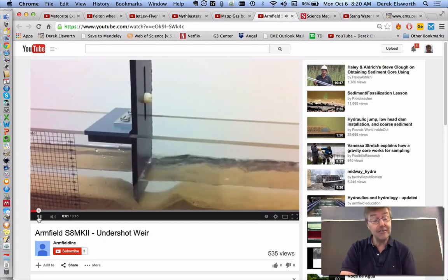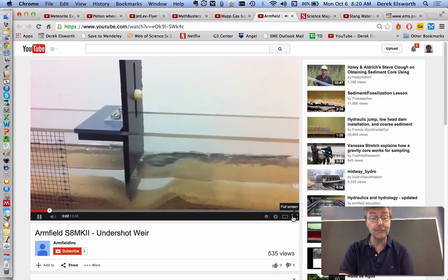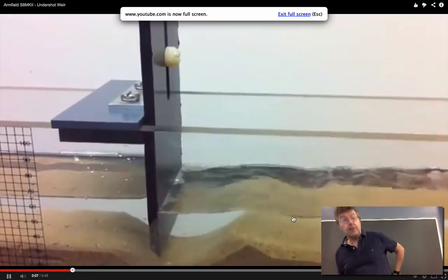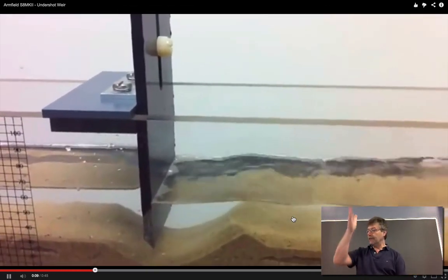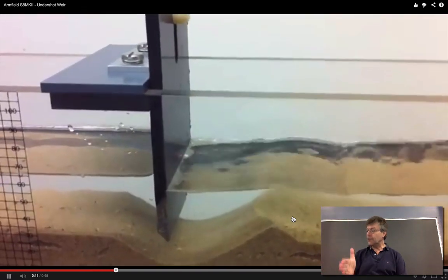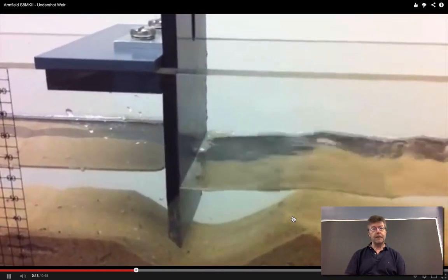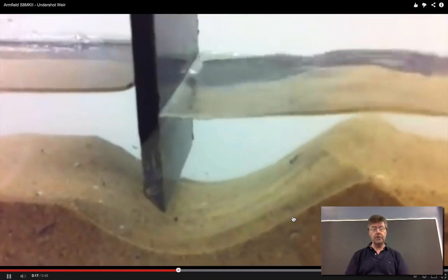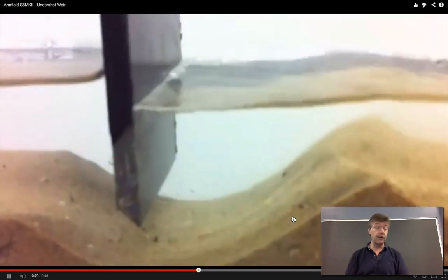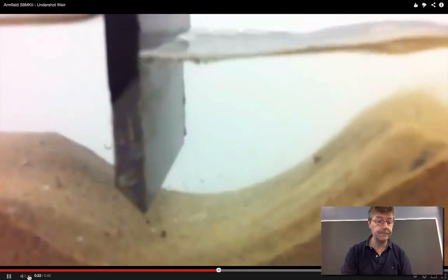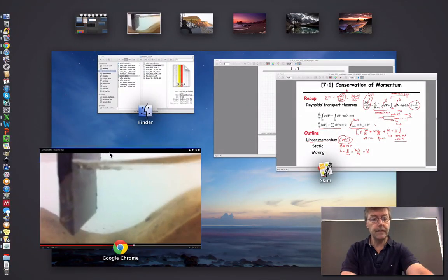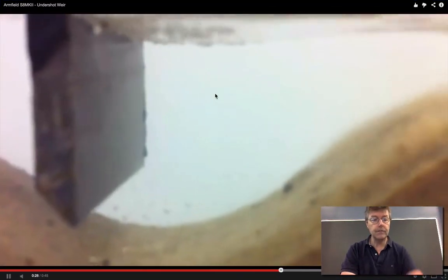Yeah. So we can also use it for fluid mechanics things as well. Things that we've talked about and solved using Bernoulli, the so-called undershot weir. The idea that you can change the elevation of this, the penetration, if you like, of this weir, and from measuring the upstream and downstream elevation change, you can use that to say something about the flow rates in these systems. I guess I was probably talking over the noise for that, so perhaps you won't get that on the recording.